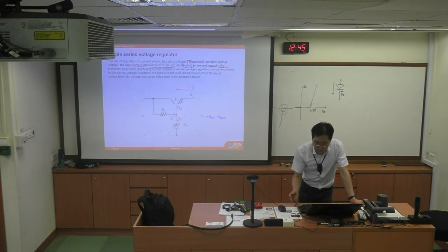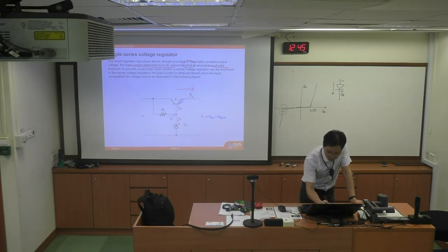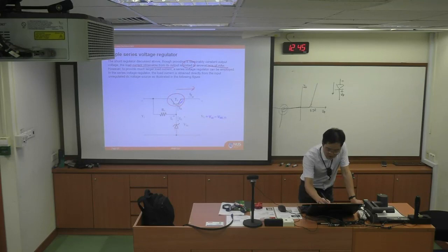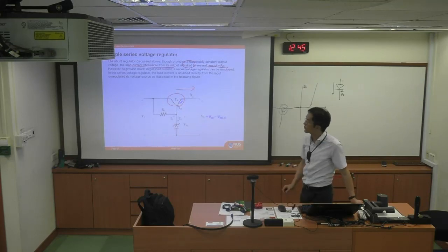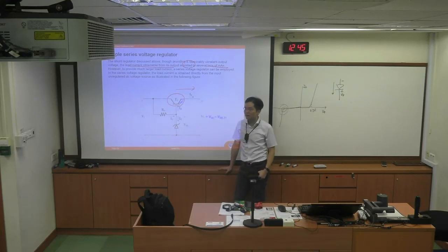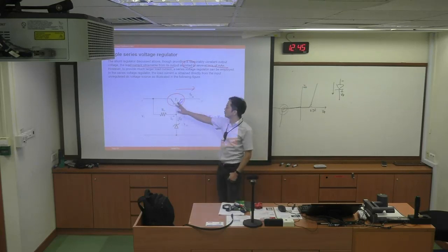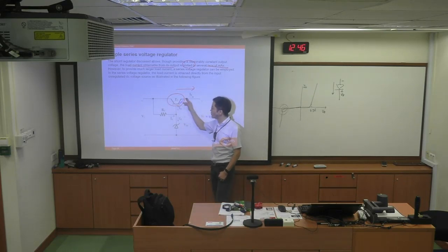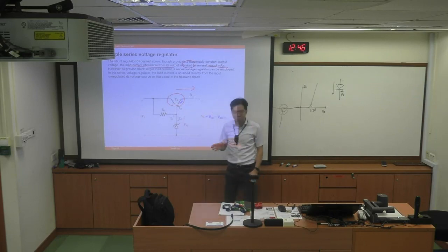You will have the transistor with the Zener diode, which has the source resistor connected, and the load will be connected to the emitter of this T1. This is no exception with an NPN. For the MOSFET version, we typically use PFET for this configuration, so I'll come back to that. But for BJT, we typically use an NPN transistor.